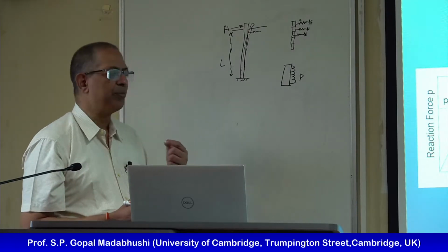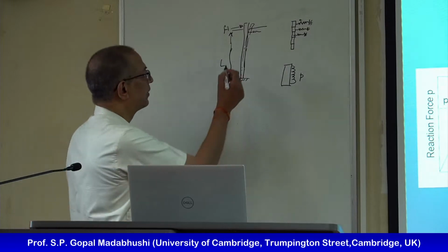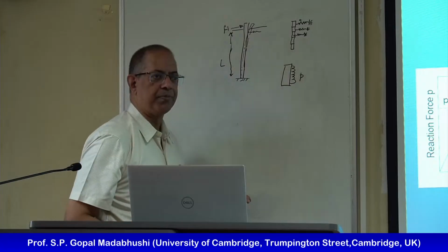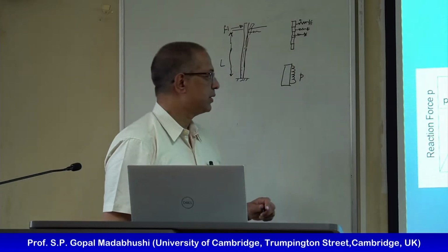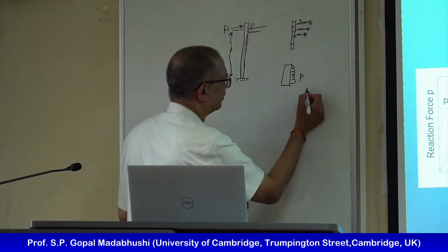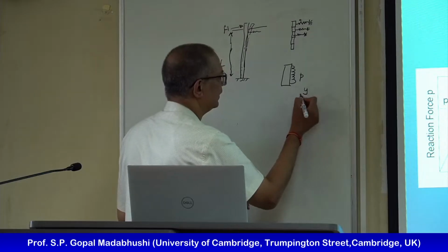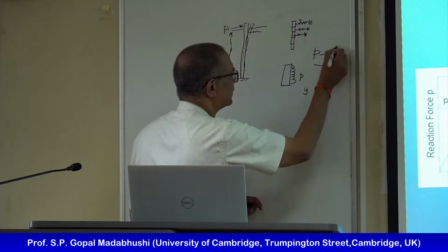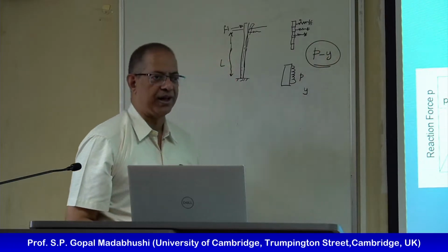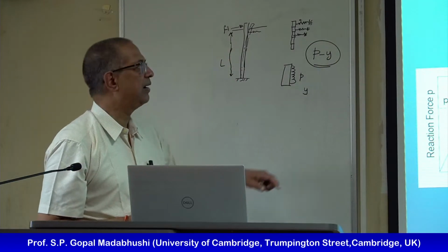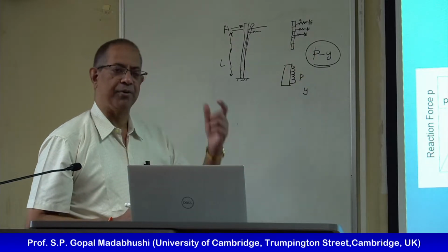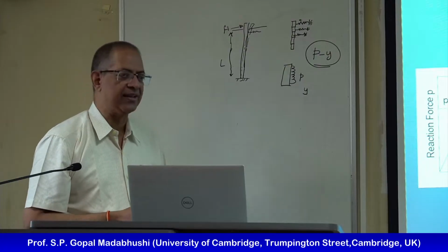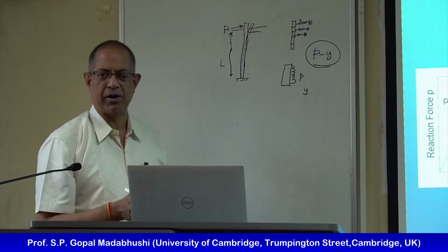So what matters is the relative displacement between the pile and the soil. That is called Y. Because we are using symbols P and Y, this is what the so-called PY analysis is. And people like Meyerhof, Reese, Matlock and the rest have done this for ages for laterally loaded piles in clays and sands.